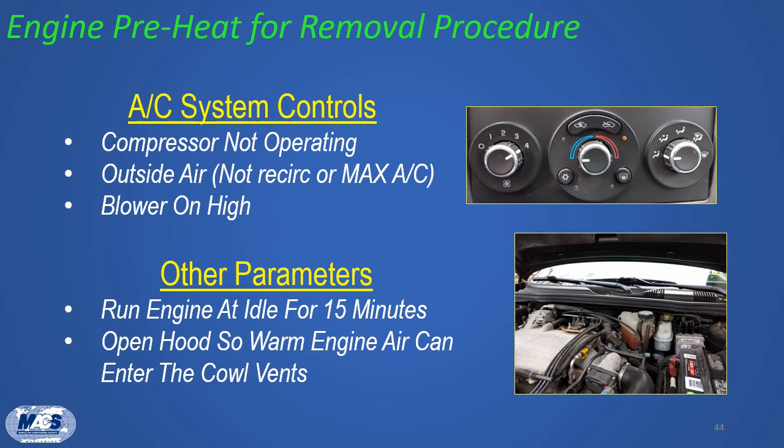So at this point, you're going to set the dashboard controls to have the fan or the blower motor all the way up on high. You're going to turn the temperature knob all the way to cold. You're going to have it set for outside air, not recirc or MAX. And the compressor is not going to be operating. You're also going to start the engine and run it at idle for 15 minutes and keep the hood open this whole time so that warm engine air can enter into the cowl vents.